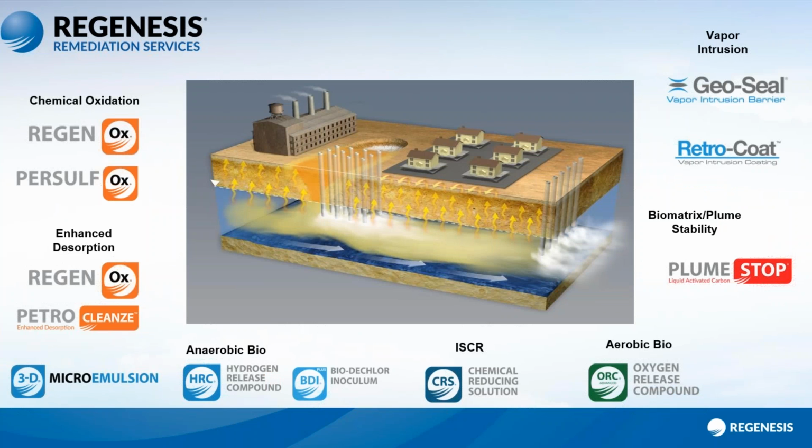Now, just so you know, the 3DME is an electron donor, and that is applied as a dilute suspension. It has unique subsurface distribution characteristics. In its molecular structure, it contains oleic acid and a polylactate, and this structure allows for an enhanced distribution, which is going to be critical for some of the testing that we present later today. And then once in the subsurface, the 3DME is going to have a controlled release of the organic acids into the aquifer, and that's going to in turn stimulate reductive dechlorination in the aquifer for about 2 to 3 years.